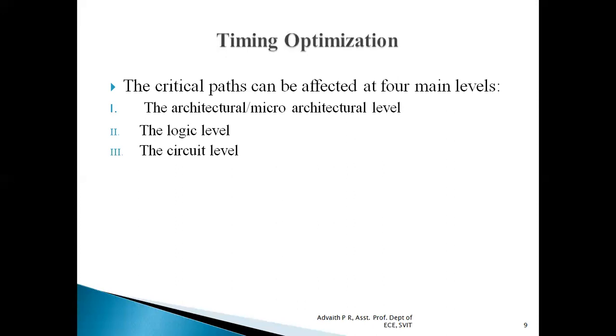In this level called the circuit level, the designer will have provision to choose which CMOS logic to apply, what kind of technology we have to use, and what should be the size of the transistor. All these things directly affect the critical path. And finally, the layout level. The delay finally is dependent upon the layout level. The floor plan is of great importance because it determines the wire length that can reduce the delay. Good cell layouts can also reduce parasitic capacitance as well.